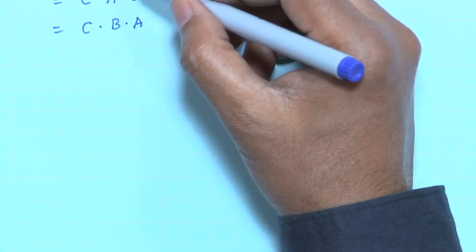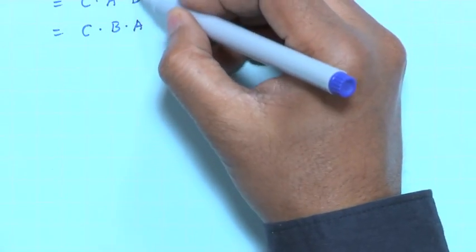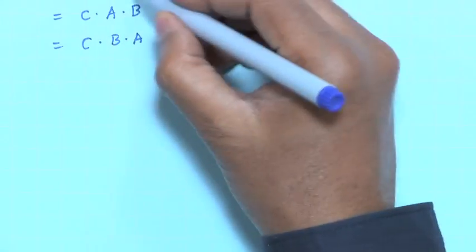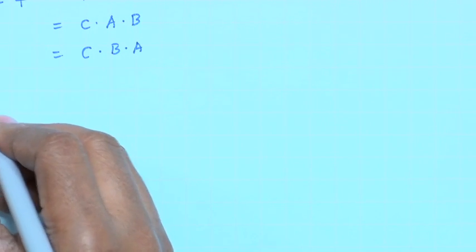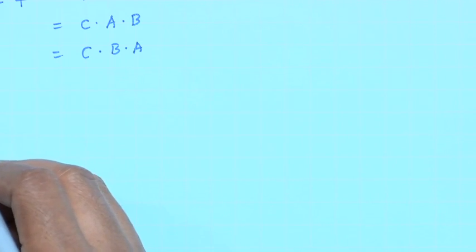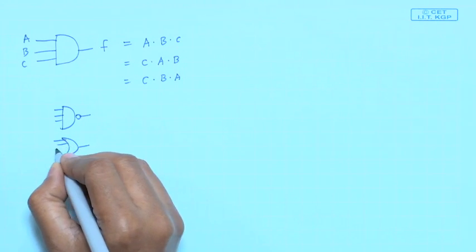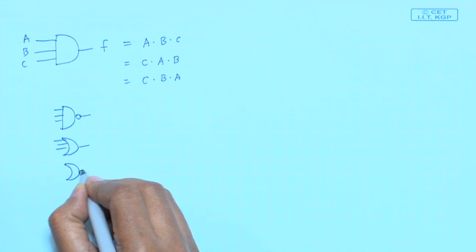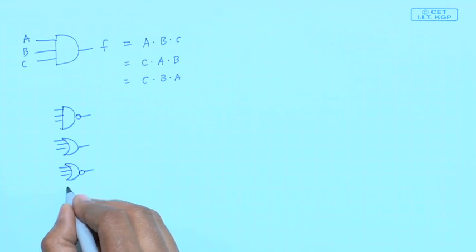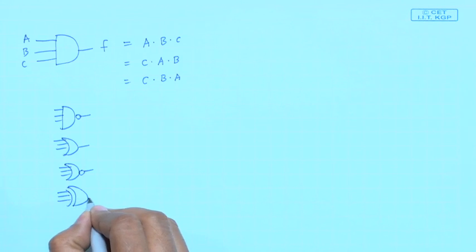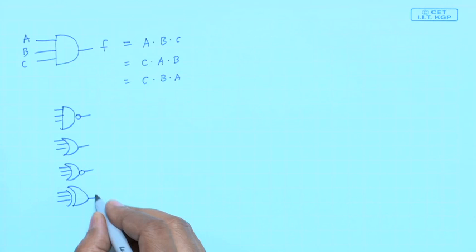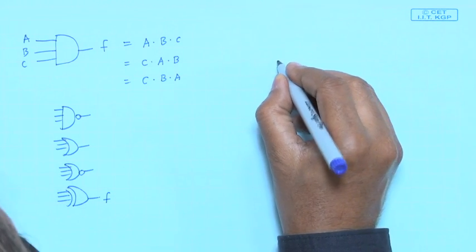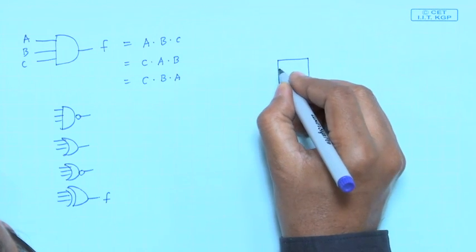So, you can use the rule of commutativeness to prove this easily. Okay. Similarly, the basic gates are all commutative in nature, NAND, OR, NOR, even exclusive OR. They are all commutative in nature. You can swap your inputs in any way you want, the output function will not change, they will remain functionally the same. But suppose I have some other functional block, let us say a multiplexer.